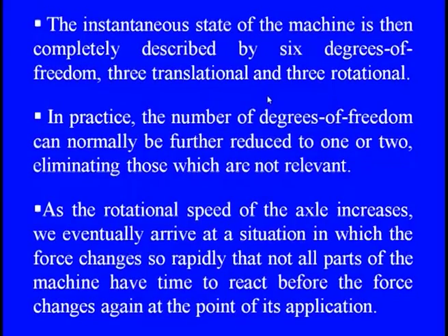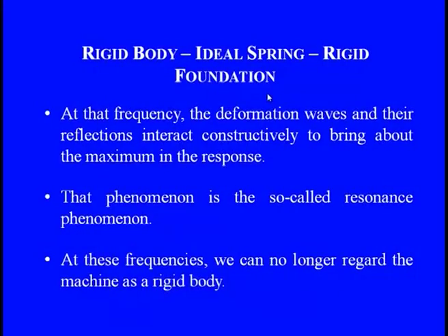And when you see the time, the machine does not have the time to react before the force changes. Then we can see that there is a clear change in the exciting frequencies with these components. And at these frequencies, the deformation waves and their reflections interact constructively, meaning in a continuous way, to bring about the maximum in the vibration responses.